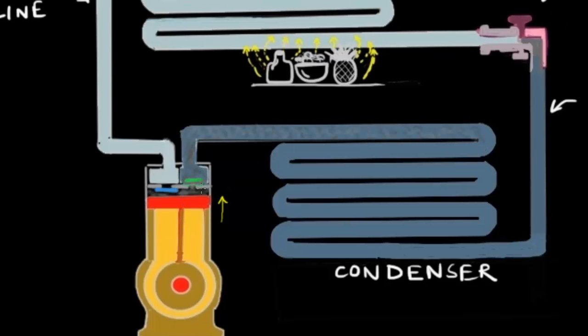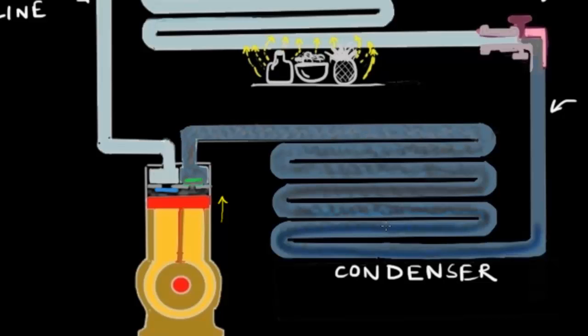So as the piston is all the way up, all the gas from inside this compressor chamber is going out to the condenser. And what's happening here is that the high pressure gas happens to be at a higher temperature than the surroundings, which could be just ambient air of your room, or it could be a cooling agent, like circulating water.